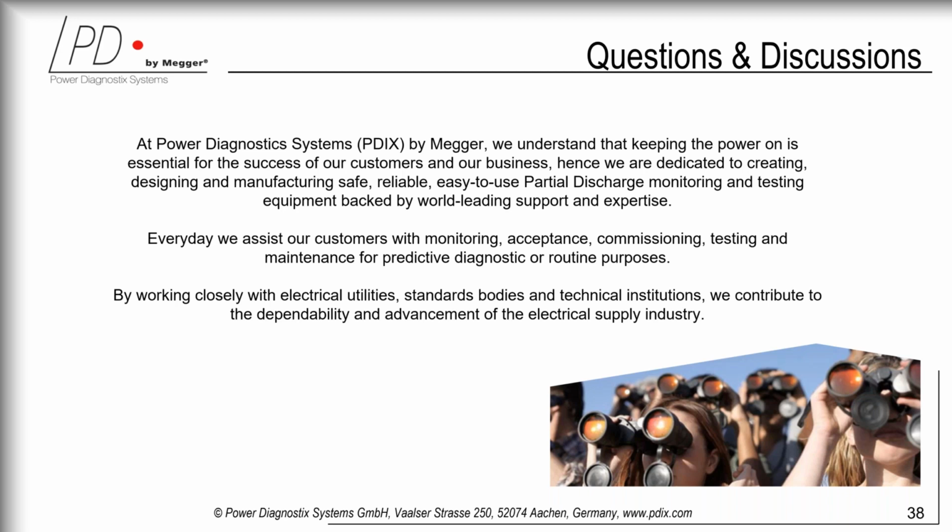I know we did find failures in composite bushings in the past, some of them during factory acceptance tests, some of them at site. The signal we receive from the bushing is similar to the signal that we see from a calibrator signal. So we can see from the spectra and from the pulse shape analysis of the PD signal where it comes from approximately.